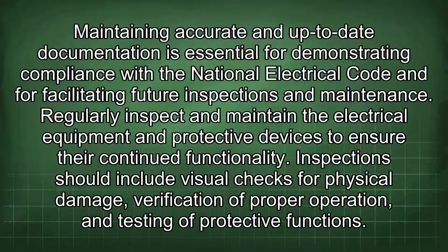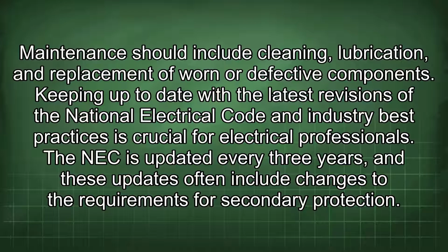and maintenance. Regularly inspect and maintain the electrical equipment and protective devices to ensure their continued functionality. Inspections should include visual checks for physical damage, verification of proper operation, and testing of protective functions. Maintenance should include cleaning, lubrication, and replacement of worn or defective components.